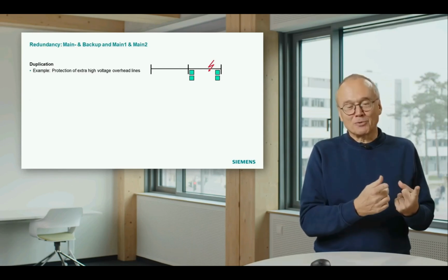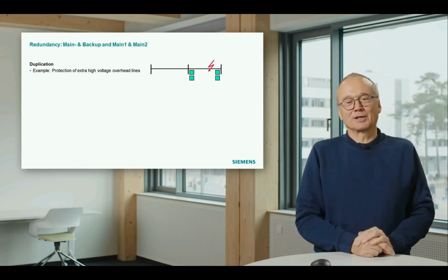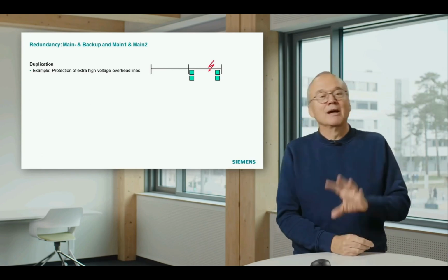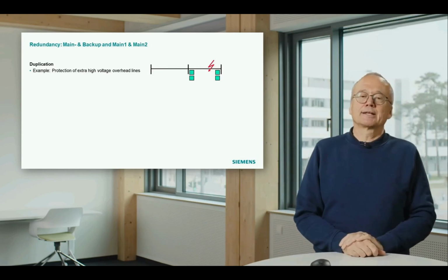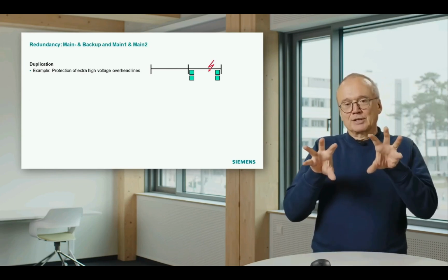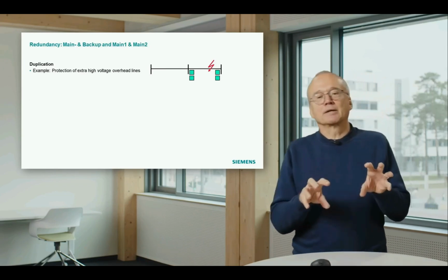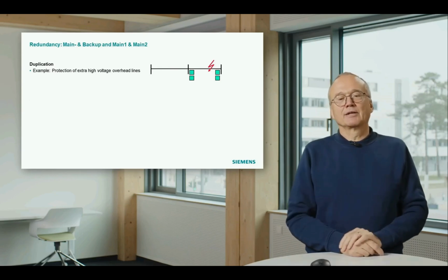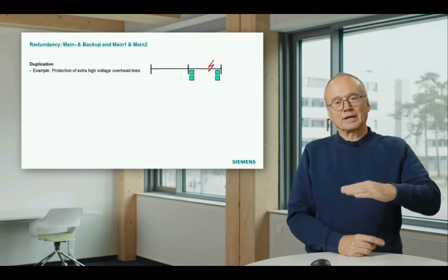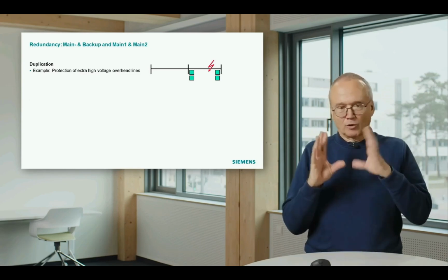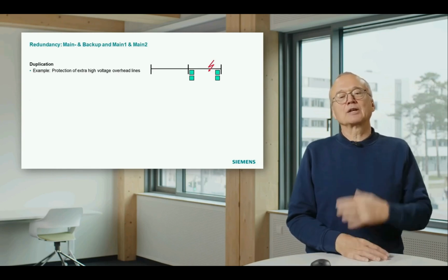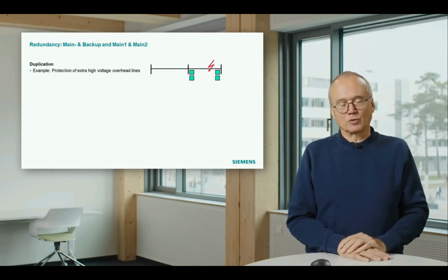That means you will only trip the breaker if both give a trip signal. That is again this discussion about dependability and security. But state of the art in this context is both relays or both protection schemes are independent. That means both relays can trip. That means you can even take one of the two protections temporarily out of service for maintenance or some changes. Then the other one will remain in operation, and if there is a short circuit, it will trip.